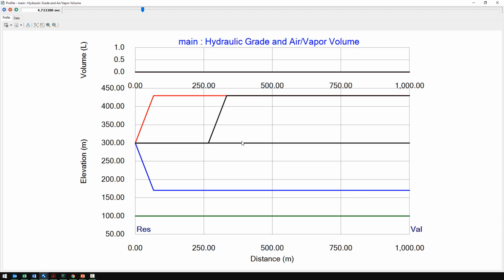So this is a very important point. Without the presence of friction in your pipe, there is nothing to dampen the surge wave, and it will bounce back and forth forever. So it's the friction in your pipe, the resistance from friction, that will reduce and dampen these pressure waves over time.